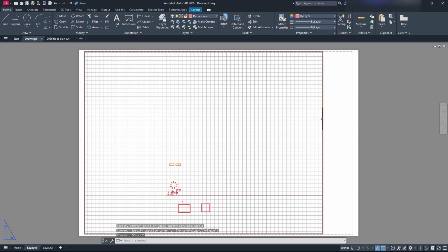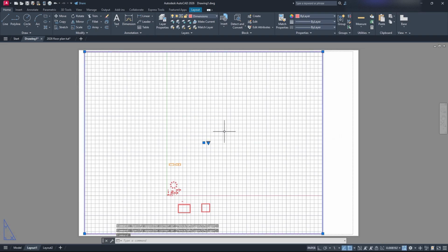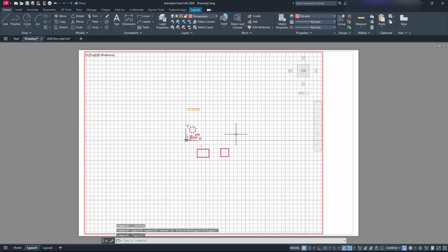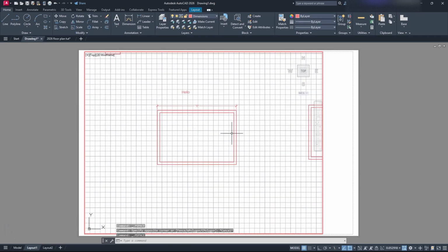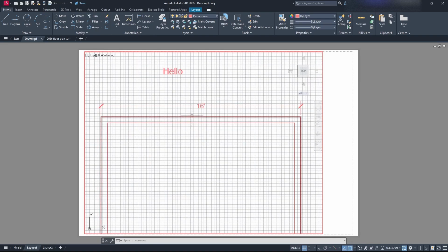Once that's done, you have to click on the outer barrier. If you click on the inside, it's not going to do anything. You can't just click on the inside and select it. You have to click on the outside. What you want to do is double click into your viewport, and then you can scroll. If you don't double click into your viewport, you're not going to be able to move. You're going to want to find what your drawing was, and you can see here that my dimension styles and my texts are showing up regardless of whether I zoom in or out.